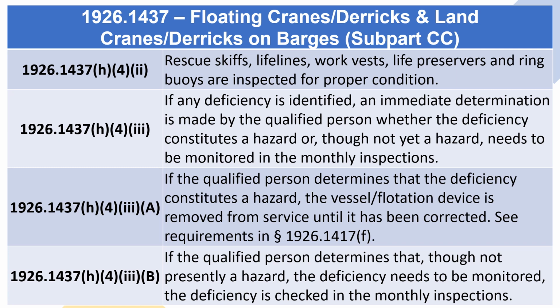1926.1437 H4-2, rescue skiffs, lifelines, work vests, life preservers, and ring buoys are inspected for proper condition. 1926.1437 H4-3, if any deficiency is identified, an immediate determination is made by the qualified person whether the deficiency constitutes a hazard or, though not yet a hazard, needs to be monitored in the monthly inspections.